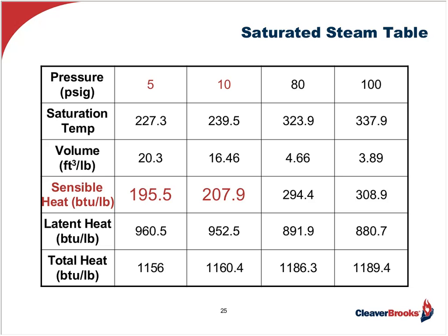Point is, if I can raise that feed water temperature coming into the deaerator by returning more hot condensate, I can reduce the sensible BTU requirement from my boiler's burner to make the required amount of steam to reach the saturation by a ratio of 1:1. And remember, for every 10 degree of improvement, I gain 1% in efficiency. I raise my feed water by 10 degrees, I gain 1%.